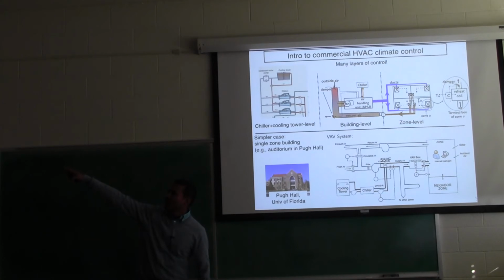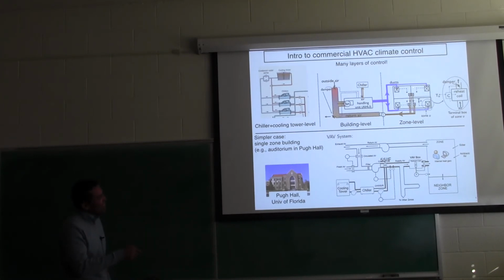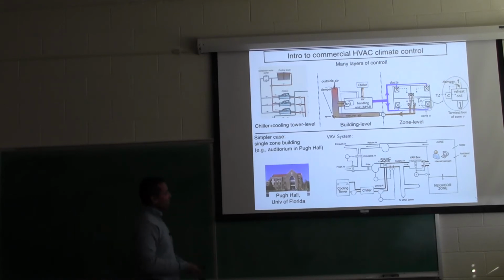If you make yourself tiny and go upstream through the duct, at one point you'll get to a box, and there's a controller that is looking at the temperature of the room, changing the dampers to change the airflow, deciding to turn the reheat on and things like that. And then it's happening at every single zone. And then this fan speed controller, there's a control loop at the air handler, up in the building, that is trying to change the fan speed so that all these zones, all these rooms get sufficient air. So it's again a very complicated interconnected system.